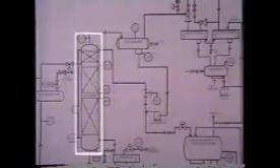A reflux ratio like 6-to-1 is generally considered a high ratio. High reflux ratios mean that a great deal of liquid is returned to the column. On the other hand, a 2-to-1 reflux ratio is considered a low ratio. The reflux ratio to be used in a column is determined by the system engineers. It depends primarily on the mixture to be distilled and the design of the column.